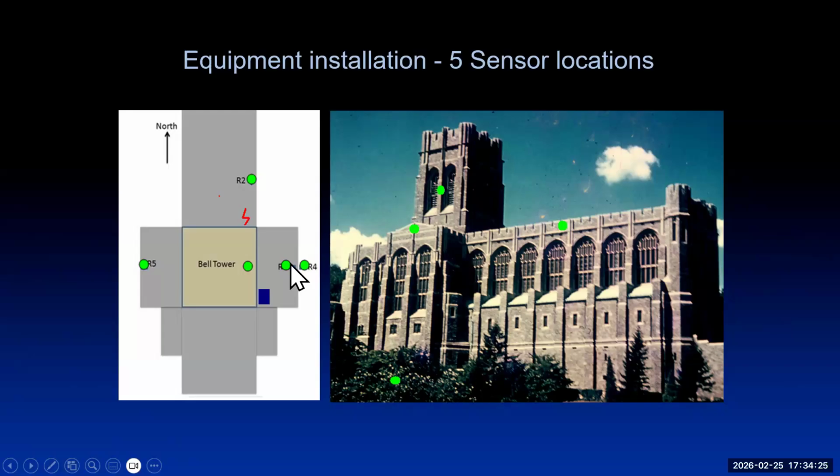What we found was, and I think we've identified something before, we found down at the ground the peak particle velocity was relatively small. We had a 12 times amplification when we were up in one of the transepts, which was furthest away from the explosions which were being done to prepare ground for a new building.